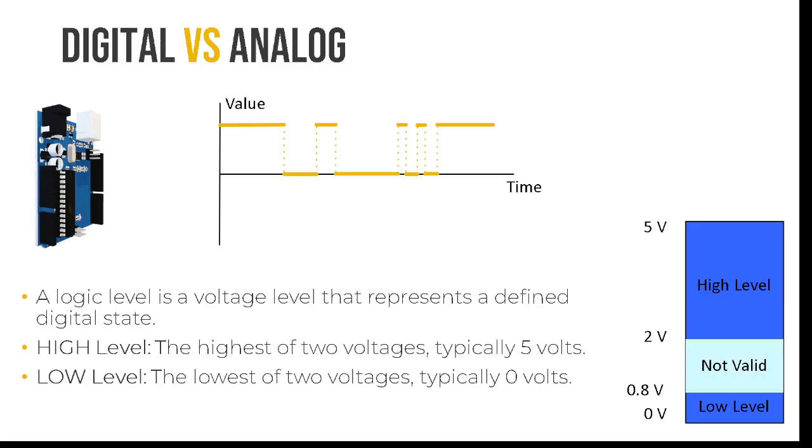In our Arduino, a logic one is whatever value greater than 2 volts, right? And zero is whatever value lower than 0.8. Those are the thresholds that you have to detect that. If you are in this zone, you can read whatever thing. It depends on the state of the microcontroller. So please don't send 1 volt there. You will not know what's happening.